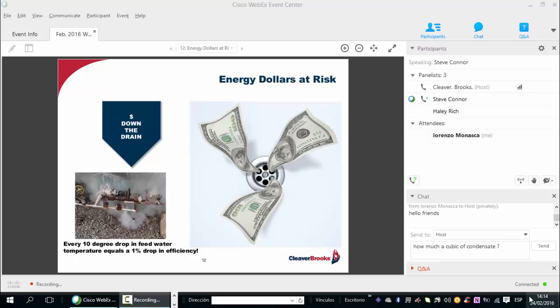And what you see on the screen now, with what appears to be a leaking pipe, is actually an open condensate line exhausting liquid gold to the atmosphere. This is costing this company thousands of dollars annually. And in many cases, no one is aware, or most tragically, in some cases, they just don't care. Hey, gas is cheap today. But believe me, the days of 22-cent per therm gas, or $2.20 per decatherm, and oil at $30 or less, it's not going to stick, and you know that. It's all going to be rising as soon as this glut that we have in this world is exhausted.